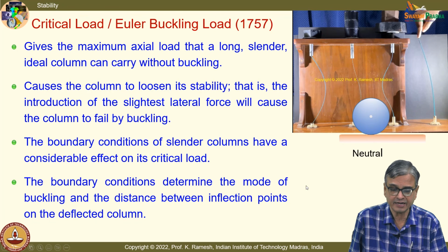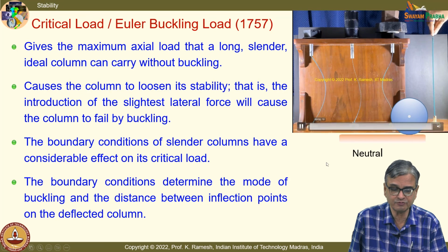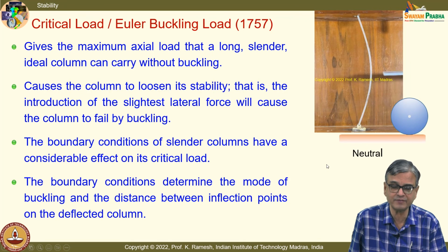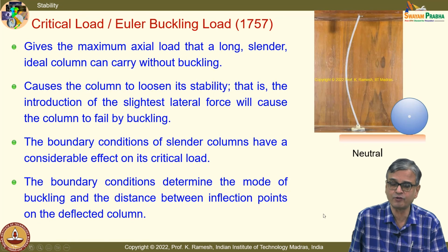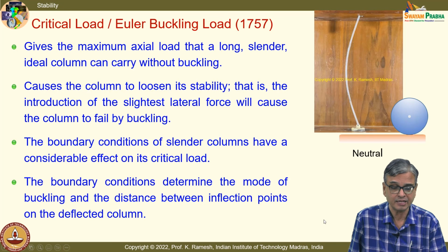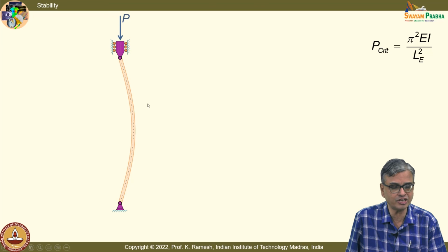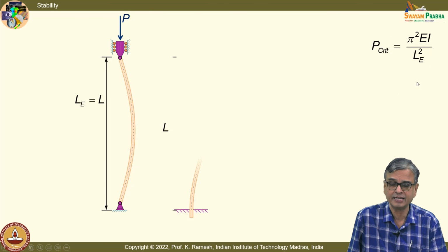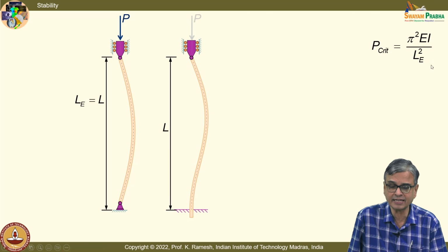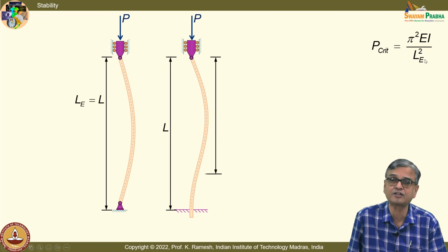Okay, and the experiment gives you truth, and this is one of the experiments which is very, very expensive, and people also found application for the buckling. Engineers are very clever, they don't let any physical phenomena go unutilized, and you view the critical load from a different perspective. You take the hinged column as a basis, and you have the critical load as pi squared E I by L squared, and you visualize other boundary conditions with an equivalent column length.